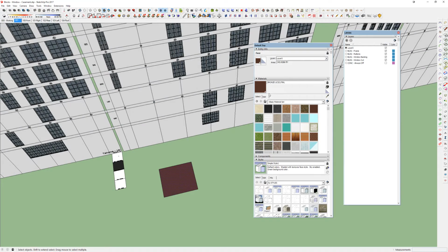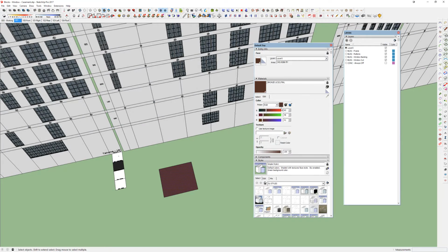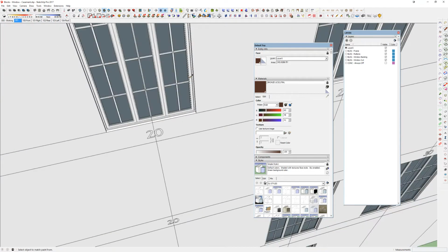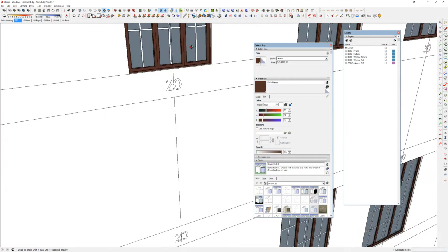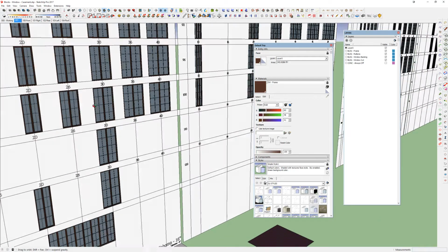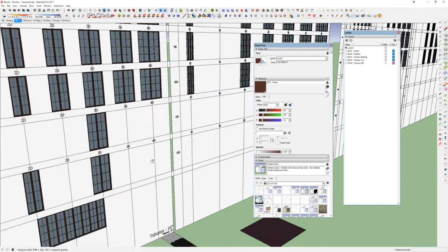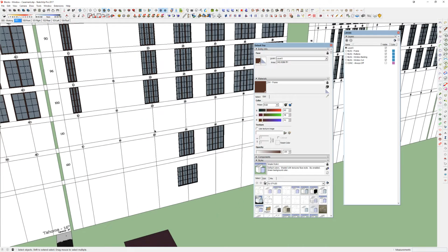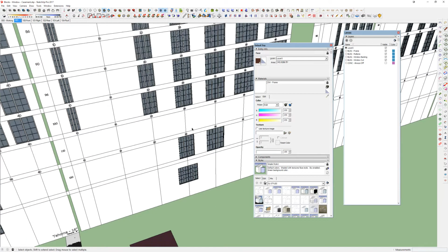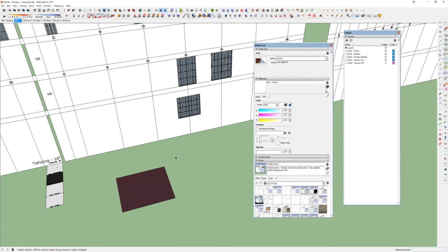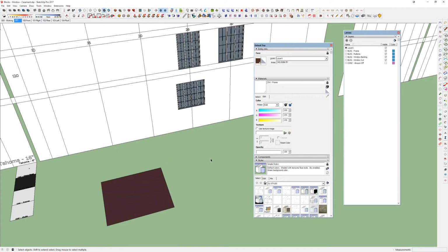There's two ways I can do it. Obviously, I can either come to edit and just remember this RGB of 85, 48, 41, and I'll pull this up and change it to 85, 48, 41. And you can see that every window I have has changed to that bronze color. But I'm actually going to undo, because there could be even a faster way.